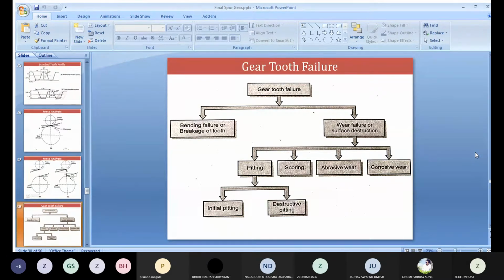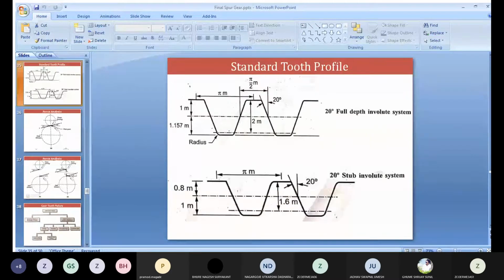Now see here, of course, a gear has a structure. You can see the structure is like that. The profile toward the top side reduces in thickness, and at the bottom side it has more thickness. It means the root thickness is always more. So any kind of gear tooth will not break from the root. It will always break from the addendum part, the top side part, correct? Whichever has the smaller thickness, from that point it is going to break.